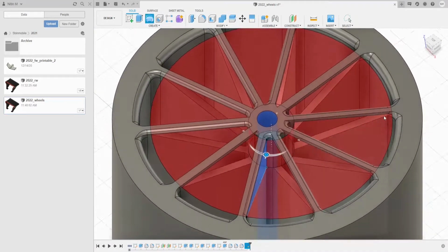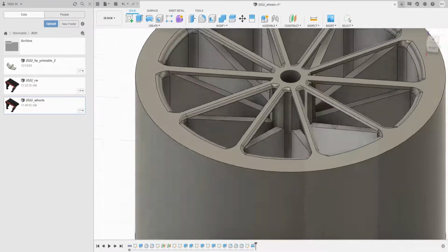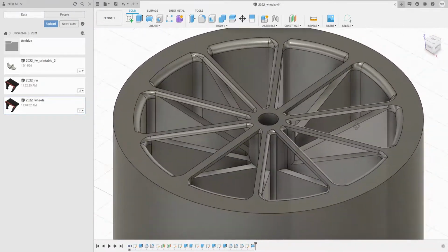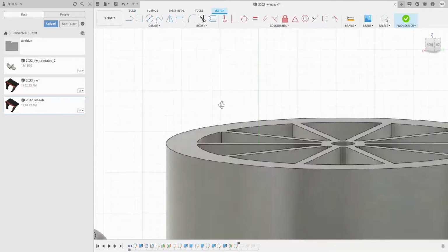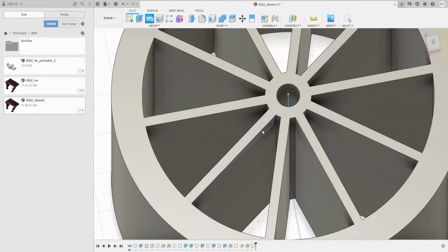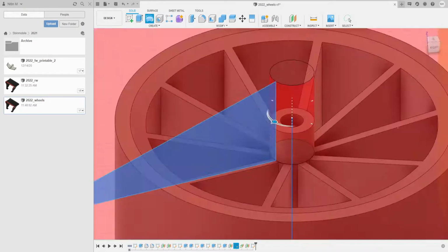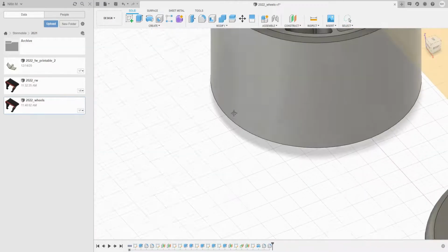After a few minutes of trying to work out what was going on, I realized that putting the sketch on the surface of the spoke offset the whole revolve by the thickness of the spoke, or 0.6mm, thus making the revolve off-center. So I went back and created an offset plane that would be at the center of the spoke to redefine the sketch plane on, and then the sketch and revolve worked out perfectly. I filleted the sharp edges and then moved on to the locking grooves I put in the tires.